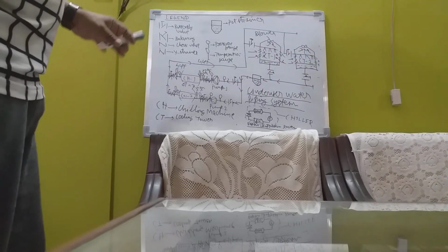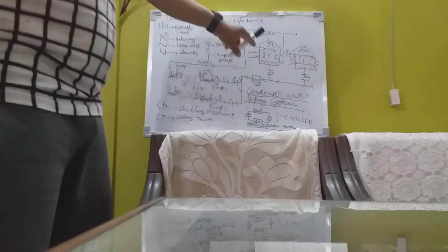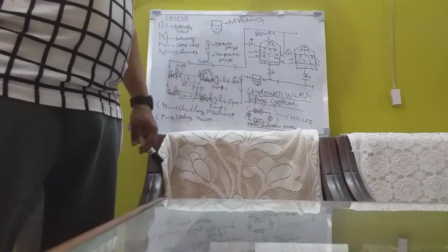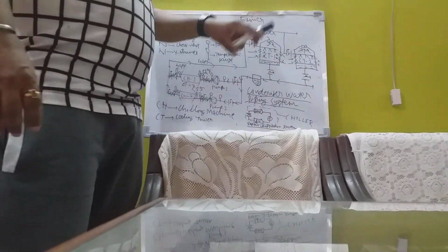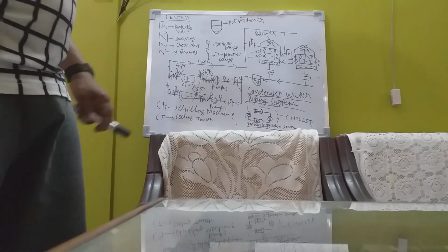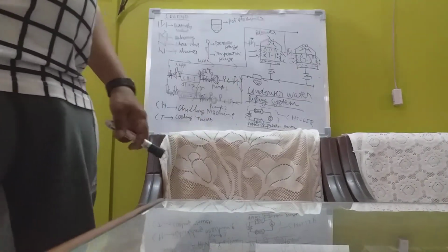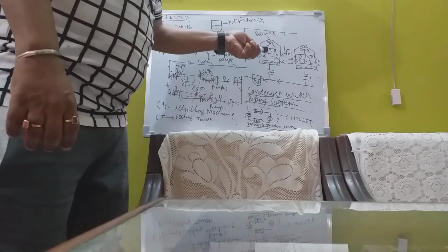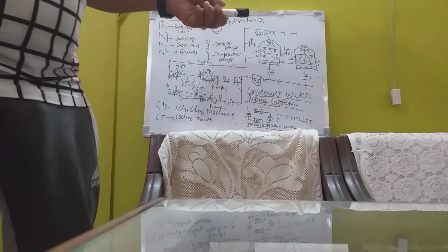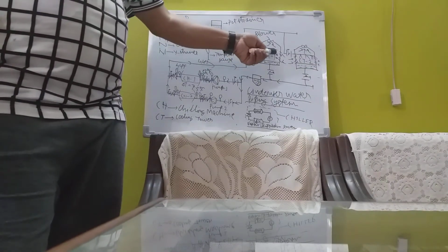So, in case of this chilled water and condenser water system, you have to understand the philosophy of the cooling tower. What is done in a cooling tower? There is a blower at the top. The blower draws or sucks air from outside. As the air flows in from outside, I drop water in small droplets, a very fine sprinkle of water.